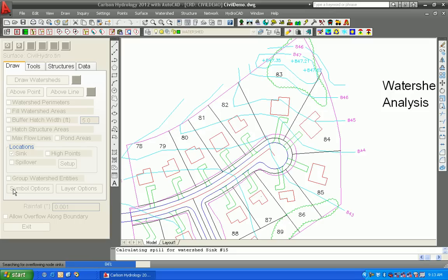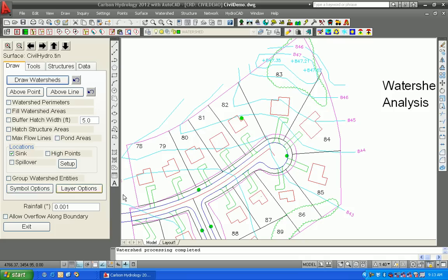In this case, for the sinks, we're going to use SPT5, and you can see that's the filled in solid circle. These are inserts, and these inserts can be used in the storm sewer command for locating your inlets at precise low points, which then lead to